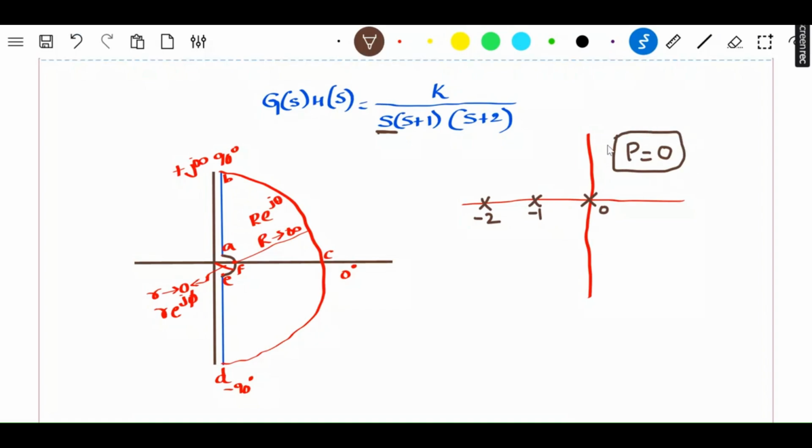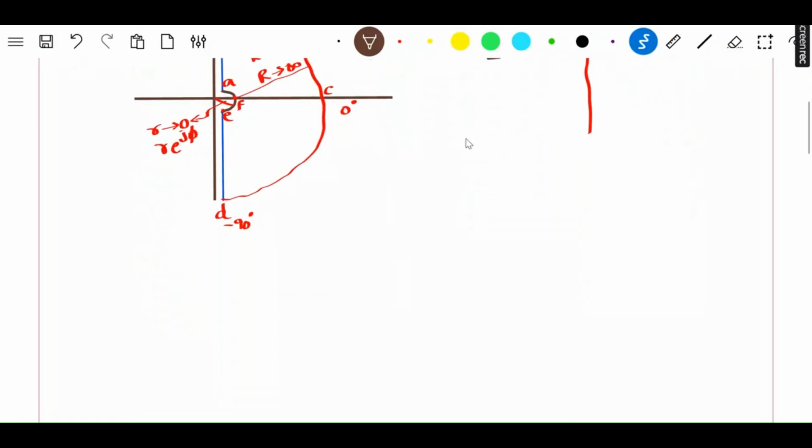Now we need to find out the encirclement. For that, we need to go step by step. For this particular problem, we are going to trace the path, and we get 4 different sections here. Section 1 is as usual the path A to B. Section 2 is as usual the path B, C and D. Section 3 is not BA now.